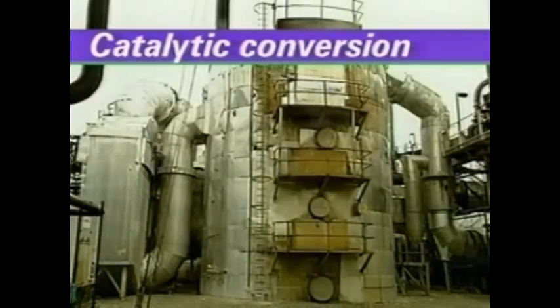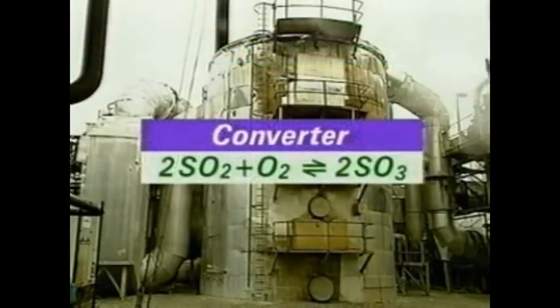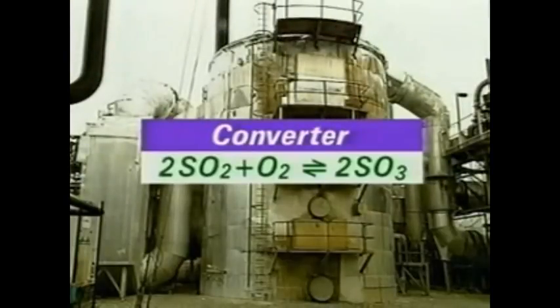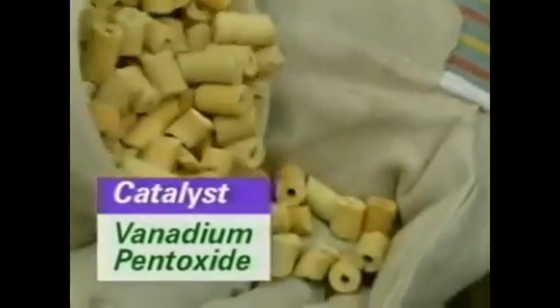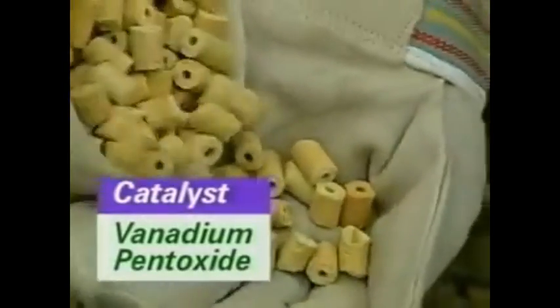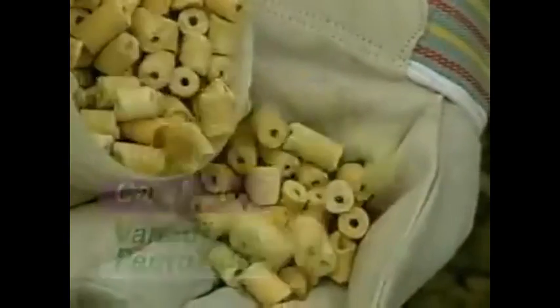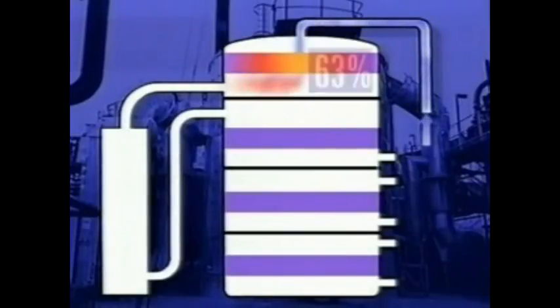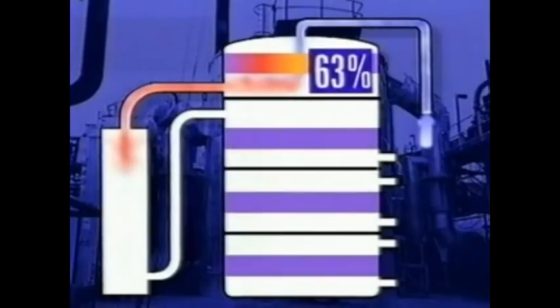In the converter, sulfur dioxide reacts with oxygen to produce sulfur trioxide. The reaction requires a catalyst, mainly vanadium pentoxide. This is most effective at 440 degrees Celsius. There are 4 beds of catalyst in the converter. The first catalyst bed converts about 63% of the sulfur dioxide to sulfur trioxide, and heat is produced.